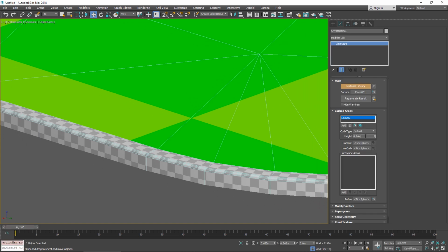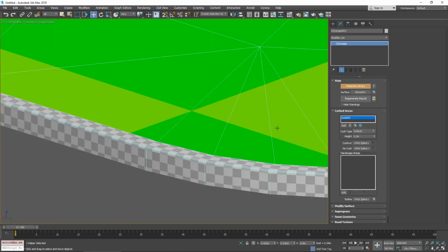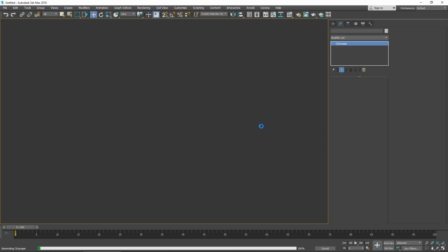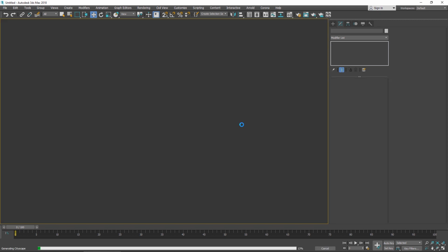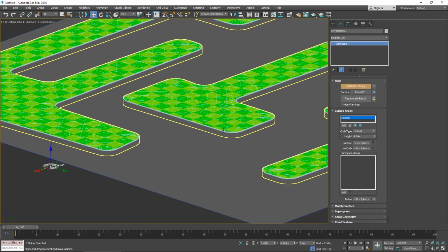The default height of the curved area is 14 centimeters, but we can change it up to 0.2 meters, or we can go down to 0.01 meters, which is 1 centimeter, or 10 millimeters. Let's bring it back to 0.14, and you can see again that every time I change something, the Generate button starts flashing in blue, which means that a change has been detected.